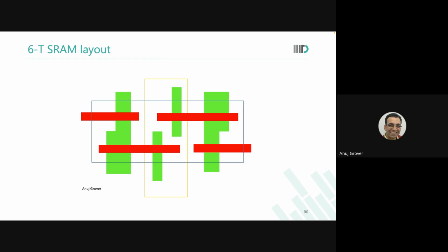Okay, coming back to this place. So this I'm taking you directly to the modern layout. You're young people, why do you want to go into old age things? So in advanced technologies, we do not like bends. In advanced technologies, we want to keep as straight lines as possible because we're already pressed by the fact that our device feature size is very, very small, much smaller than the wavelength of light that we are working with. So in all modern technologies, this is the kind of layout topology that we use.